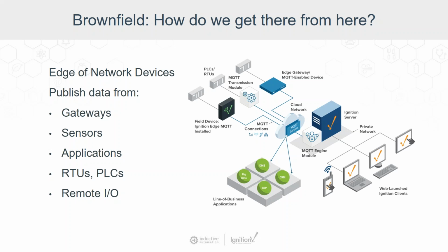And so the idea is that we can put these edge gateways in front of our PLCs, and we can start doing that slowly to transform our architectures to a more modern architecture, where then we can use modern applications, modern SCADA, to be able to take advantage of it. So that's an important part of MQTT: once we bring it to that server, there are many applications, from business applications, of course, to SCADA applications, that can consume and do a lot of interesting things with that data.